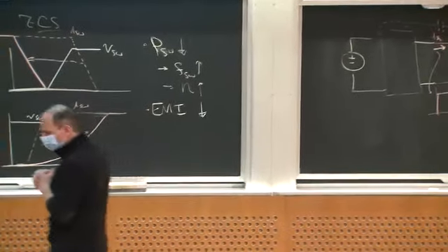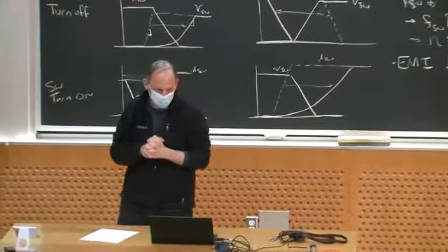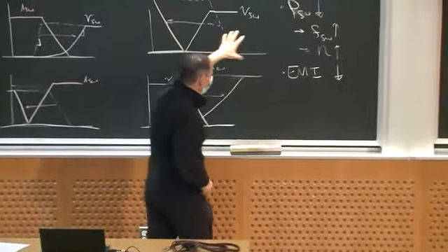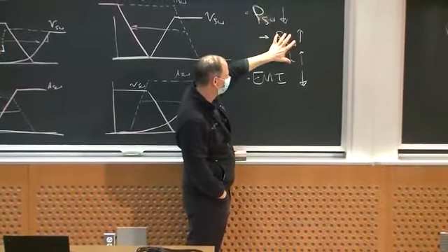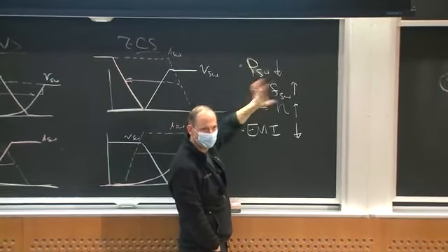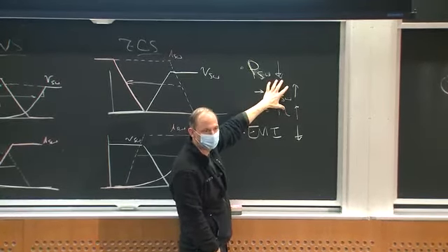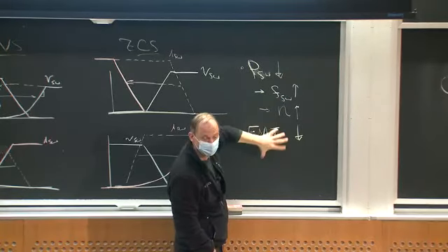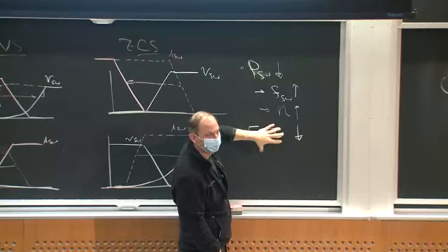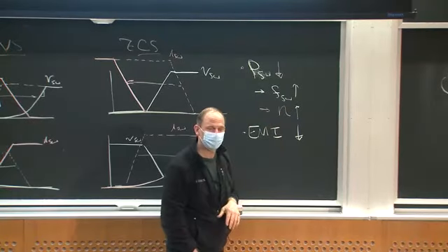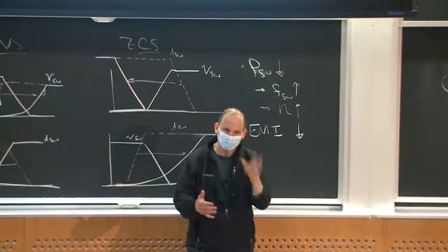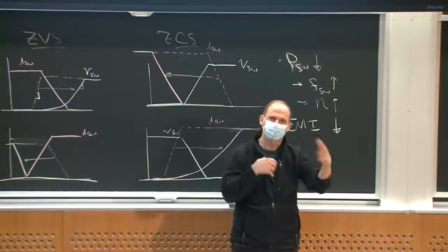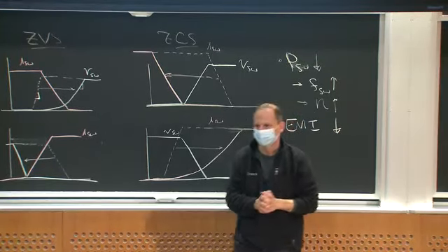Okay, so I wanted to argue that one of the things we can get out of soft switching is reduced switching loss, which lets us either get efficiency or higher frequencies, and hence possibly higher power densities, smaller component size. And for a given switching frequency, we reduce the EMI. And even when you're pushing frequency, that can help you, because you might have a high switching frequency converter that doesn't have really high frequency content. Okay.